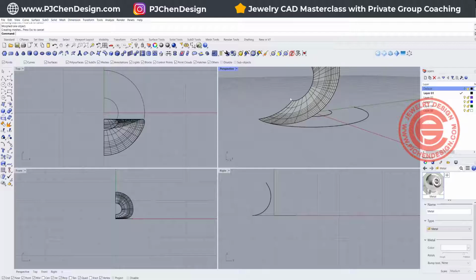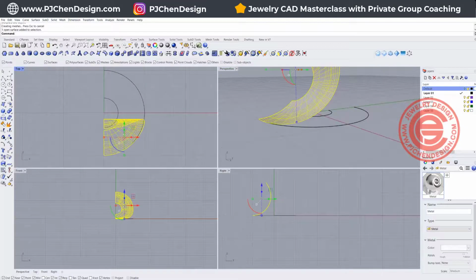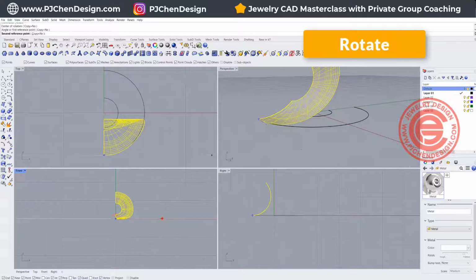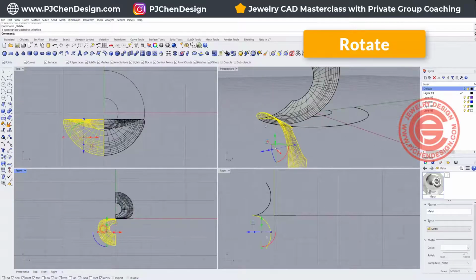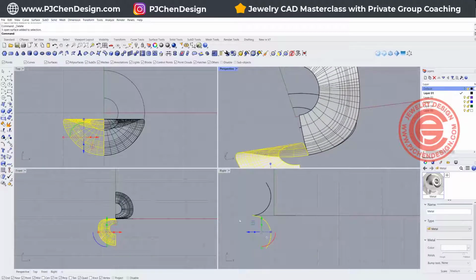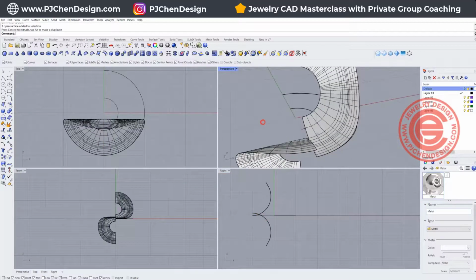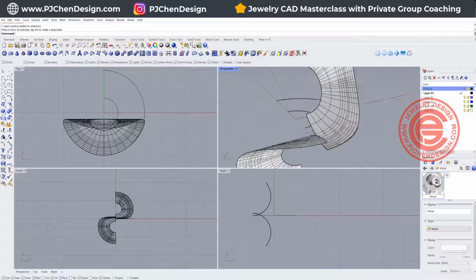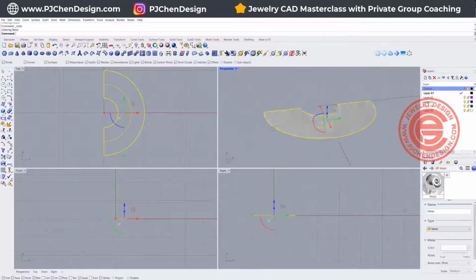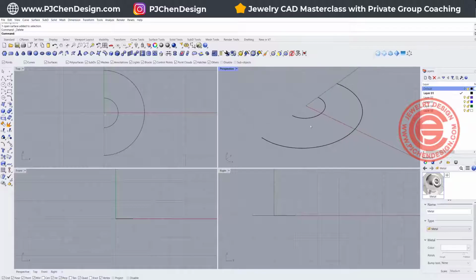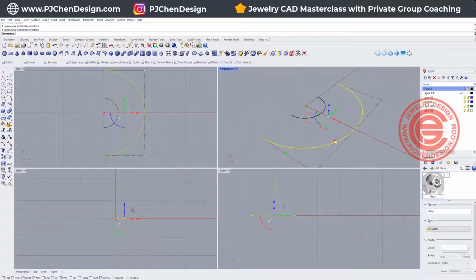Now this is curved up, so if later on, let's say we wanted to make a duplication by rotating it to the bottom, as you can see, these two don't connect because you have one going up, one going down. So the connection is not going to work. So we need to make sure they are straight. So in this case, we cannot make them into the surface first because you bend the edge of the surface. So what we can do is only deal with the curve.